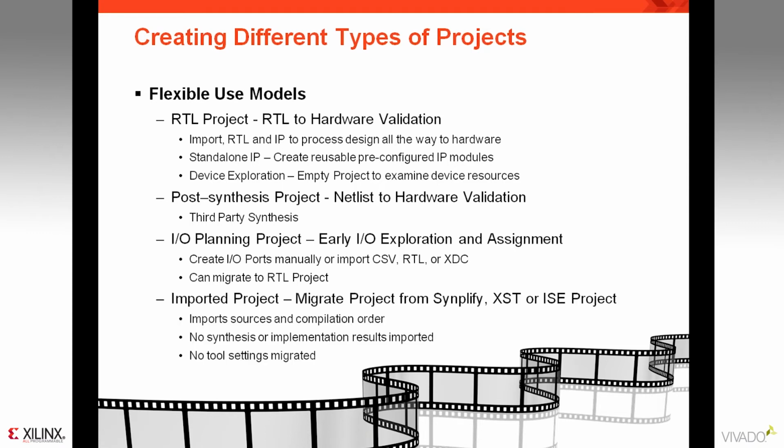And the last one is an imported project. This is to help users migrate from either Synplify, XST, or an ISE Project Navigator project into Vivado. It imports the sources in compilation order only. This is intended for people that want to move forward with this design in the Vivado design environment. So no synthesis or implementation results are imported. The assumption is that you're going to rerun them in Vivado.